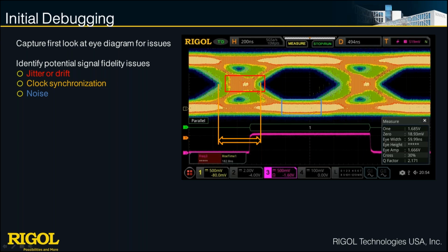The blue rectangle there in the center shows you really the amplitude noise. That's the vertical noise on the signals. That's an easy way to see it, but obviously that noise is permeated throughout the whole signal, right? So it causes us issues in the transitions, noisy transitions, noisy bands on 0 peaks and 1 peaks as well. So this is a common cause of many issues for decoding or demodulating ultimately the signal you're trying to capture.